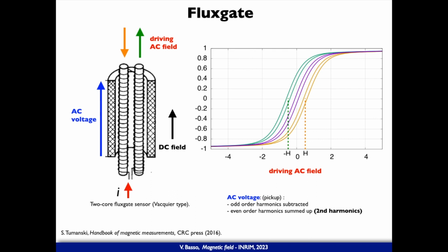In the picture on the left, you have the two bars. These two bars are made of some soft magnetic material. As you can see, you have an inner winding of a wire that for the left magnetic bar has one length of winding, while for the right one has exactly the opposite. So imagine that you let a current, an AC current for example, so you magnetize one material in one direction and the other one in the opposite direction.